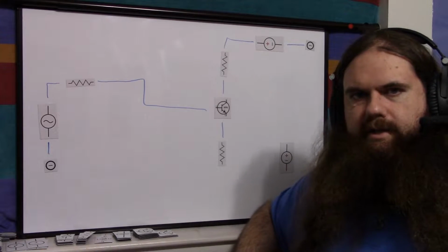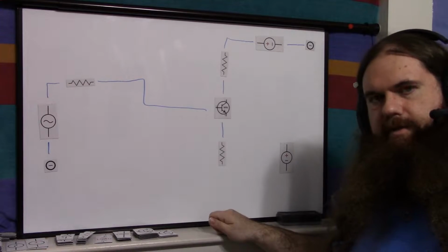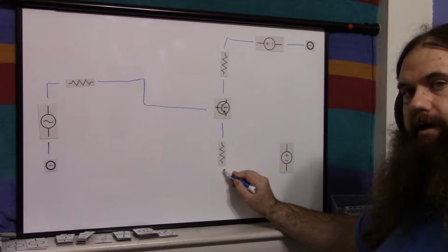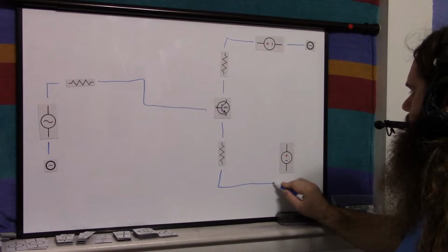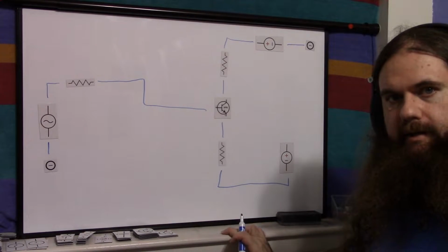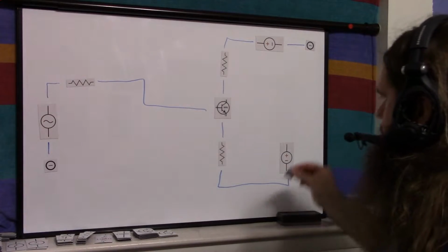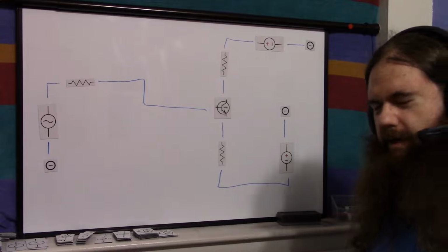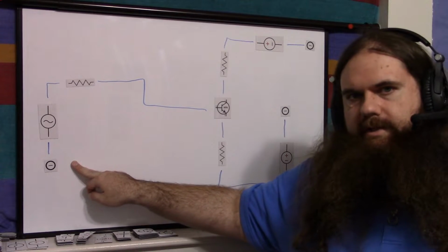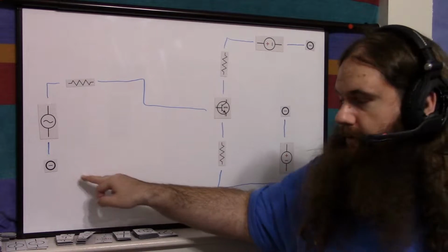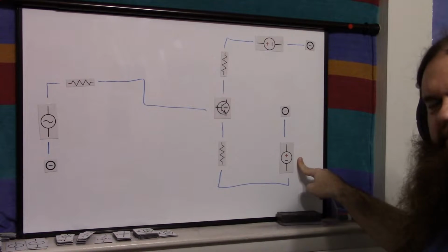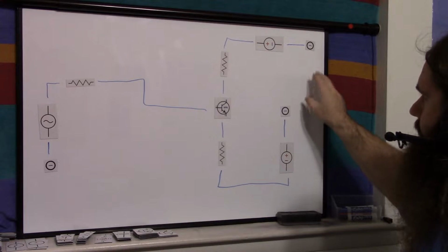Now, why is it called a negative power supply? Well, it's because of the way it connects to the reference voltage. I'm going to connect the end of the emitter resistor to the negative of this power supply, and the positive of the power supply is going to the system ground, the circuit ground, the reference voltage. So one side of the signal is at reference, the negative of the positive power supply and the positive of the negative power supply are both at reference as well.